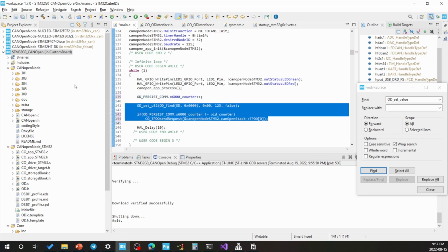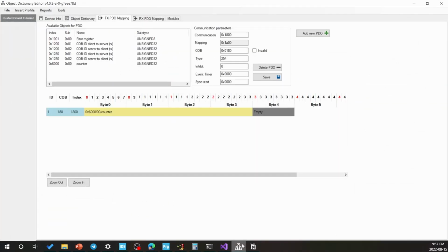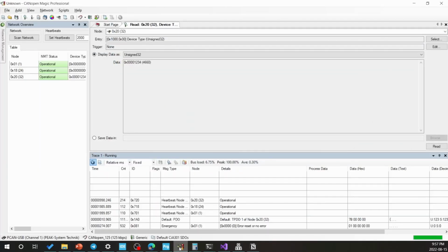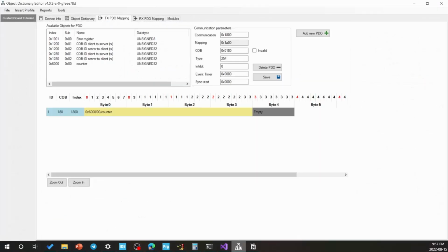So now let's talk about RPDOs. Okay, so in order to do that, I'm gonna use the F0 one. In F0, I'm gonna make an RPDO which receives this TPDO. Okay, let's do a chain. So let's transmit this every 1500 millisecond. Just check it.